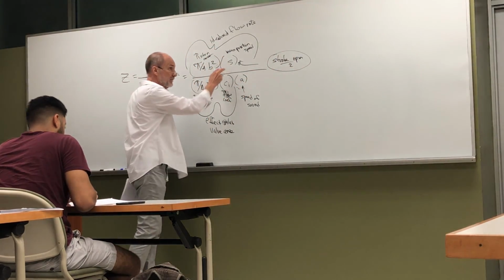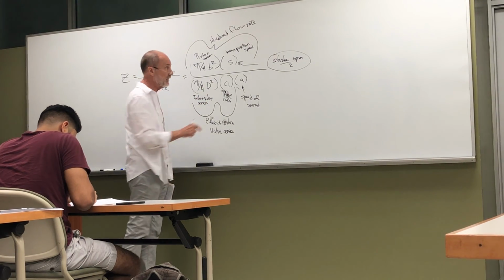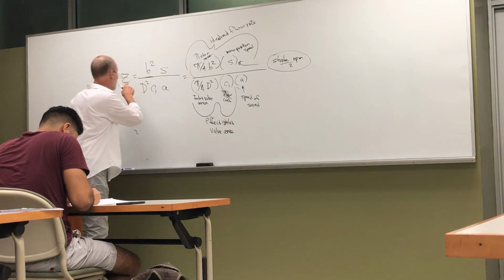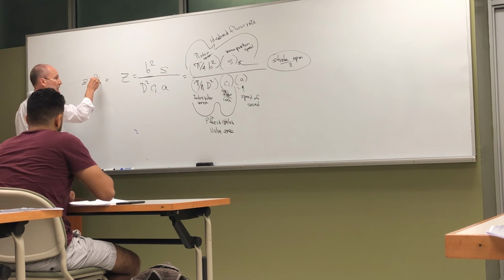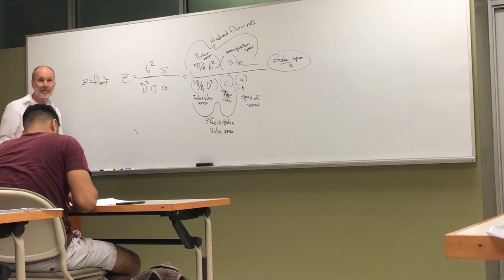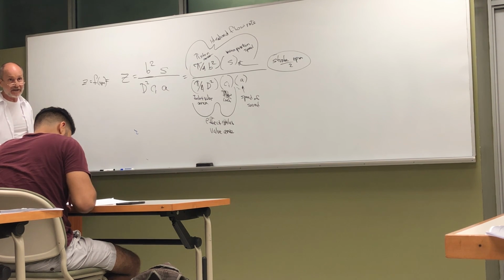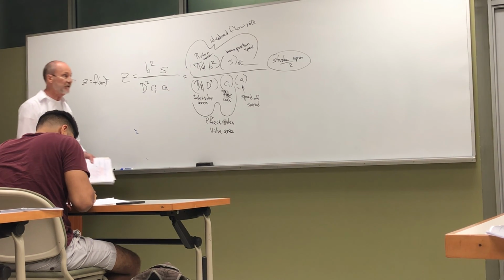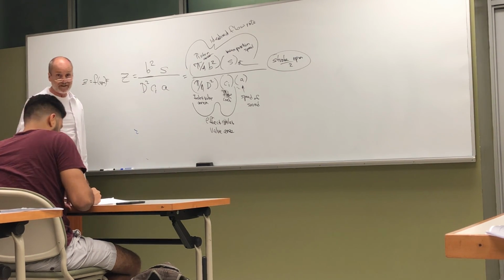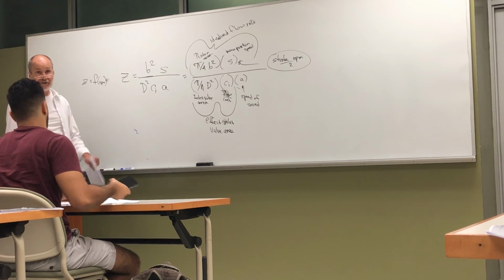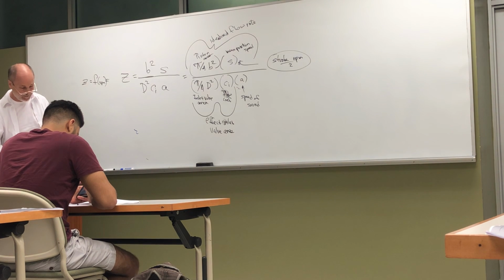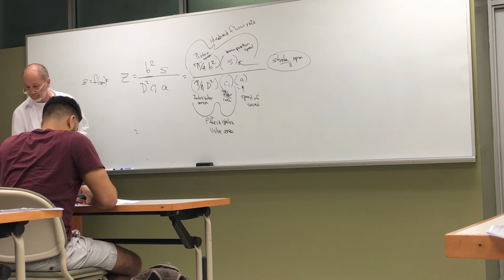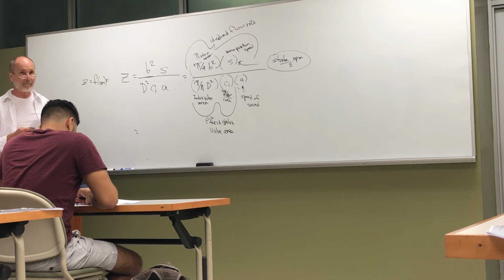So this, for a given engine, given engine geometry, the Mach index number is a function of RPM only. So as we increase the Mach index number, all we're doing is increasing the RPM of a given engine. If we're going to compare 2 different engines, then of course they can have different Mach index numbers because the geometry of the engine can be different. Right?